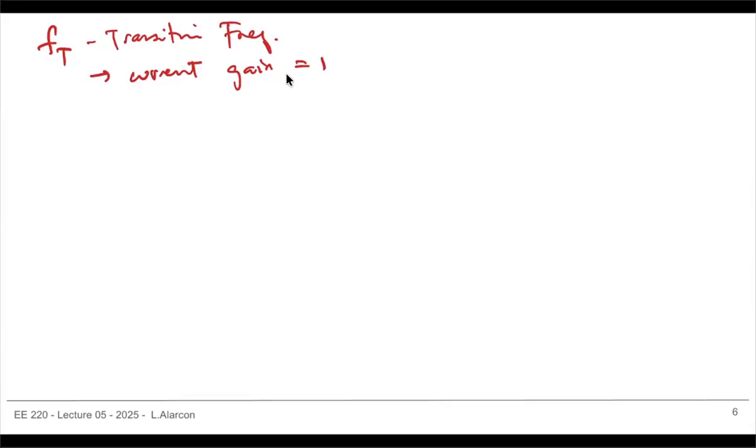It means that, okay, in small signal, I have this thing. Oh, so let me clarify. This is the short circuit current gain. That means in small signal, I want to put in some small signal current, right? And it's short circuit, then that means in small signal, this is connected to ground.